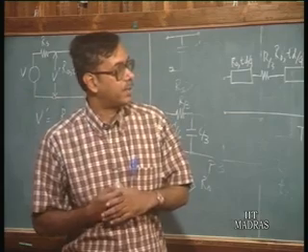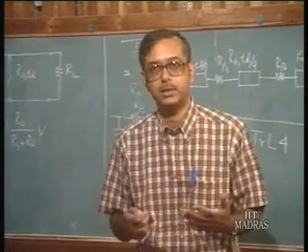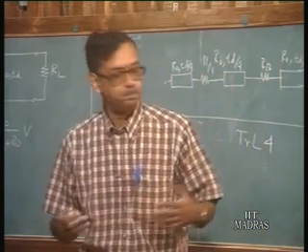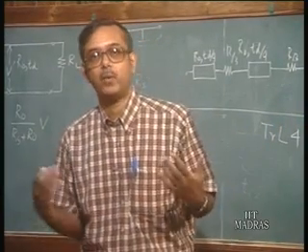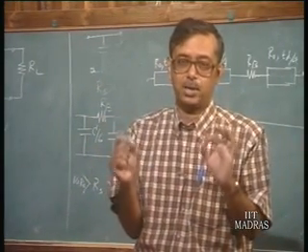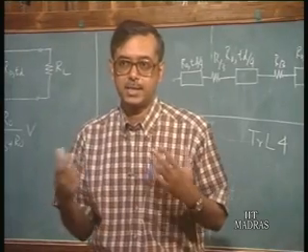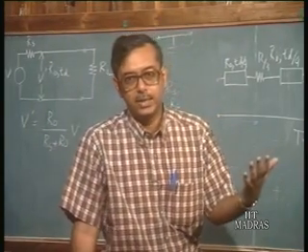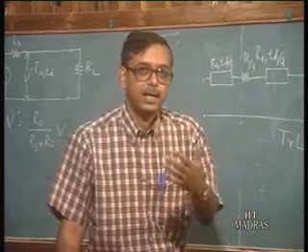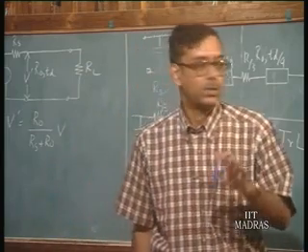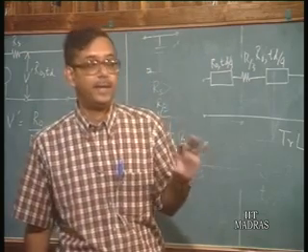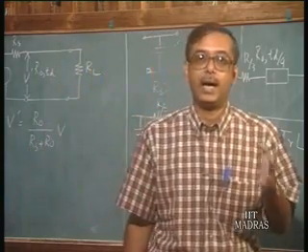So with that, we come to the end of this discussion on the effect of interconnections, and we have seen that interconnections give rise to a lot of delays as well as distortions. So we must be aware of that. We must use the correct model to simulate the circuit, that is, include the interconnection models which are available in circuit simulators such as SPICE, and then simulate the circuit to get the best results. Otherwise, when we fabricate a circuit, we may get results which are totally unexpected, and we would run into problems. So interconnections play an important role also in digital circuits, and that must be emphasized, especially when the rise times become small, that is, in modern day high speed digital circuits.